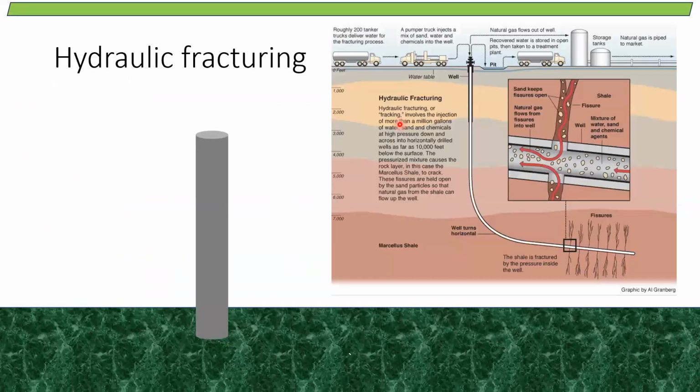So hydraulic fracturing is another important technique. Mostly this will be done for shale reservoirs, since they are tight. What is the concept of hydraulic fracturing? We are going to inject fluids, hydraulic fracturing fluids, into the reservoir formation to create fractures. So once a fracture is generated, the flow will start to come automatically into your wellbore. Generally in tight formations, the flow movement will be very less. But if you generate a fracture, then the flow will be easier, smoother, so that it will start to enter into your wellbore.